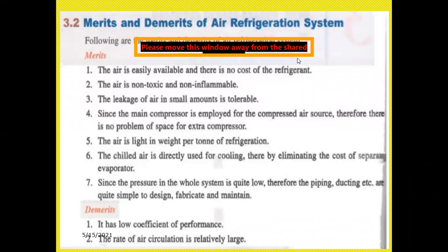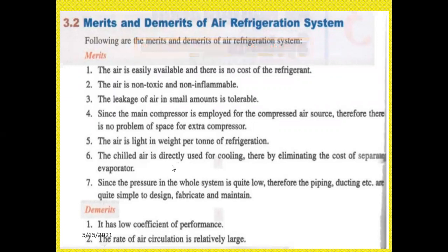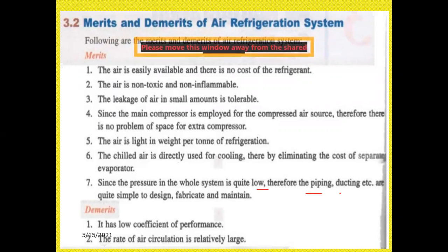So we are reducing the space, we are not using the compressor, and we are also eliminating the cost of a separate evaporator. Additionally, we don't have a requirement for purchasing the evaporator, as that is an inbuilt process. Since the pressure in the whole system is quite low, the piping, ducting, etc. are quite simple to design, fabricate and maintain.